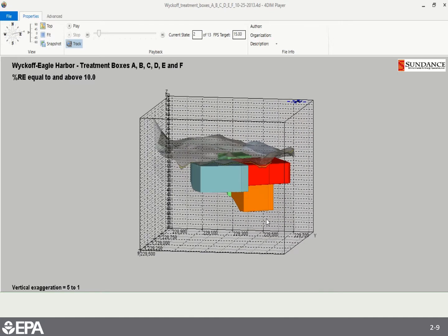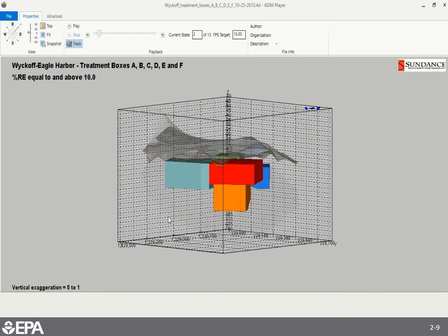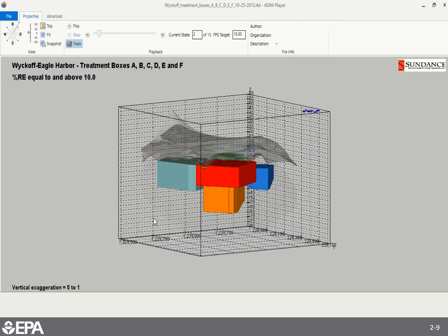And in particular, some of the treatment technologies that we had in mind based on the grain size distribution and based on the distribution of the NAPL were in situ stabilization, chemical oxidation, some sparging, and other techniques, bioremediation, because really what's driving the risks on the site are the dissolution of the NAPL materials into water and then going into either the Puget Sound or impacting groundwater. Those are the major issues.